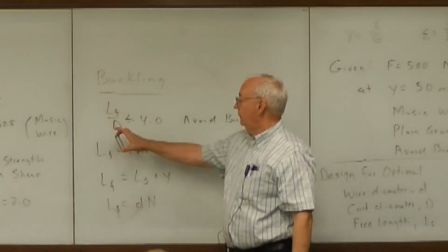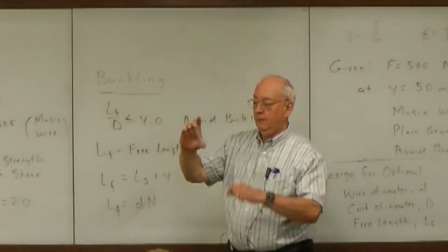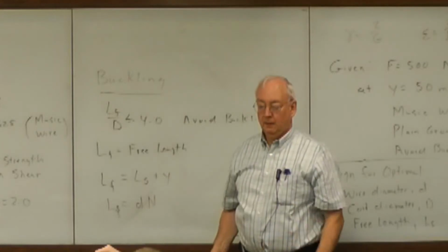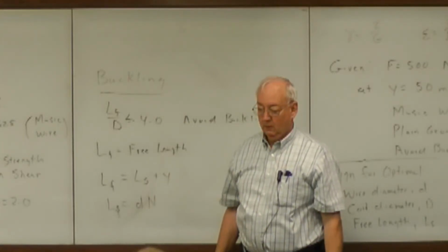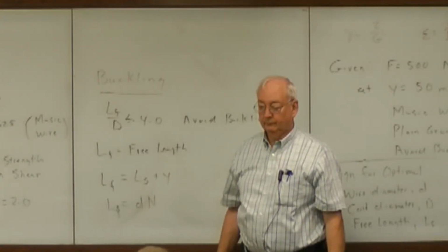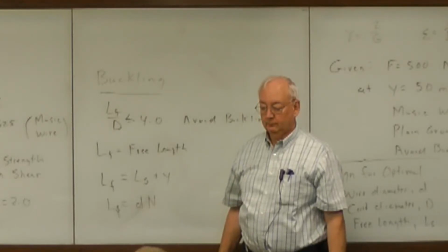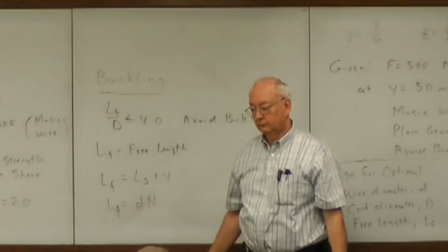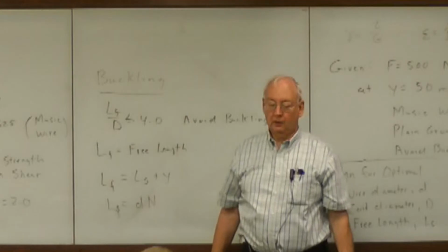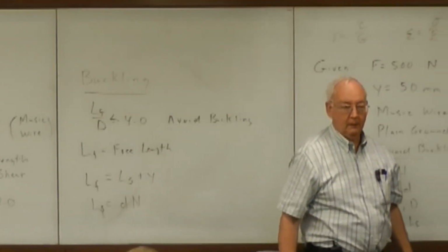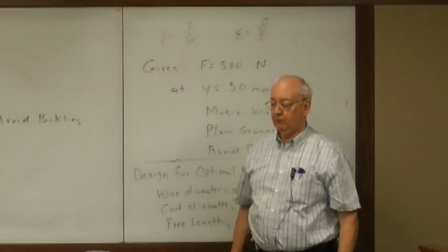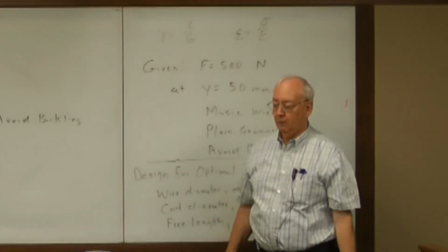Yeah, so this is coil diameter, free length. Free length is how high it is just sitting here in my hand. You were talking earlier about drawing out the wire and how that makes it stronger. Is it actually more expensive to make the smaller, stronger wire than to keep a larger portion of wire? Slightly, yeah. But cold drawing, I don't think it's real expensive. Once you start pulling, a couple more pulls doesn't hurt.